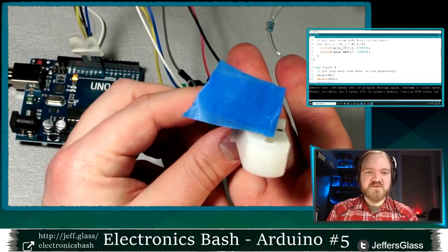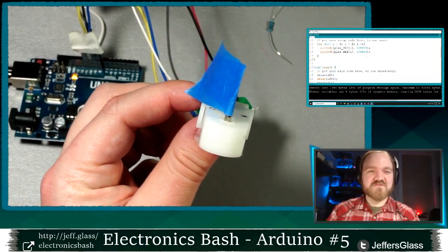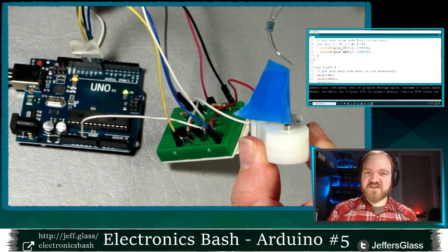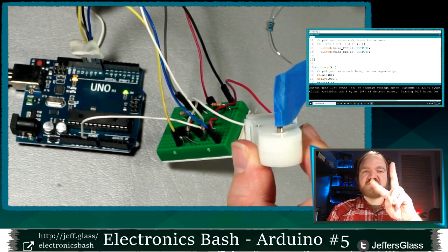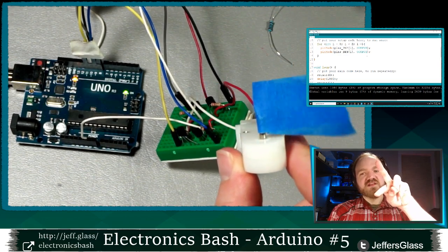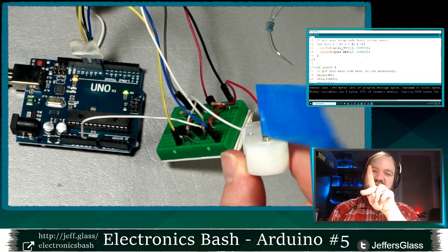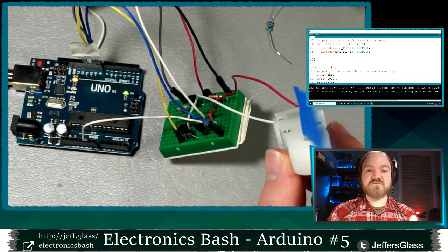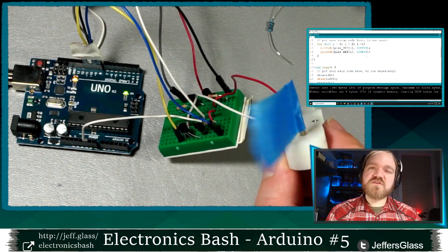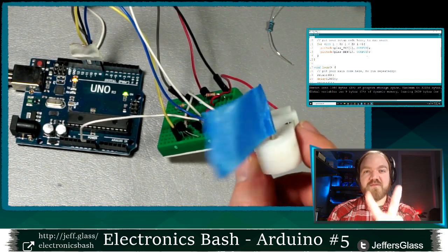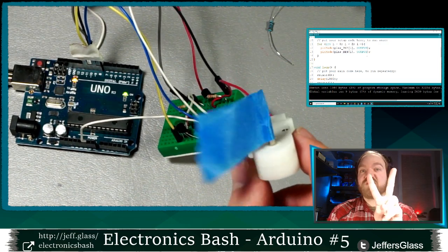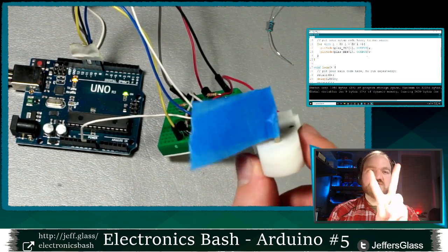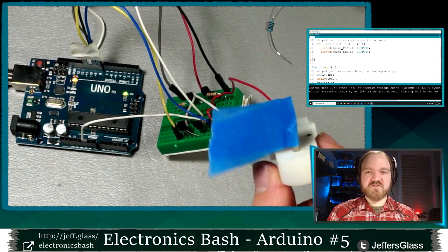So now I have the motor spinning in one direction for 1 second, and then reversing and spinning in the opposite direction for another second. So we're using that H-bridge configuration that we were building up to supply 5 volts and ground in one orientation, and the reverse and supply 5 volts and ground in the opposite orientation. So H-bridge, a super useful circuit if you ever have to reverse polarity on something. If you've ever used a bicolor LED where passing current through one way is, say, green and the other way is red, using an H-bridge is a really easy way to reverse the current flowing through a bicolor LED like that.